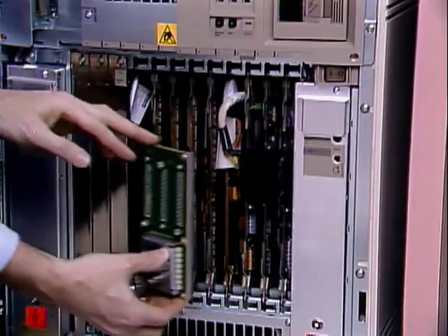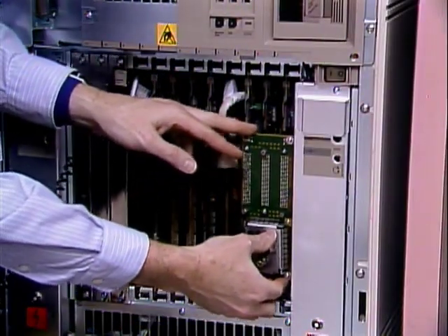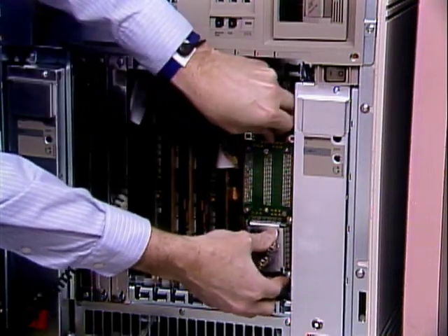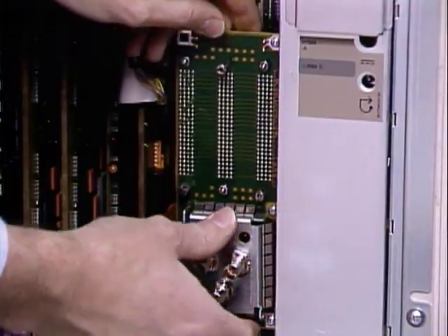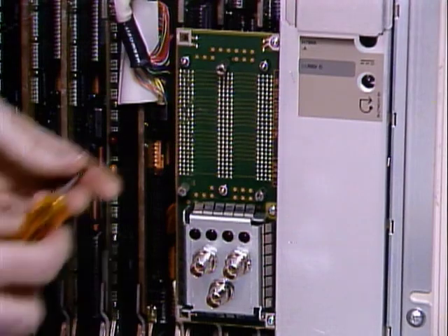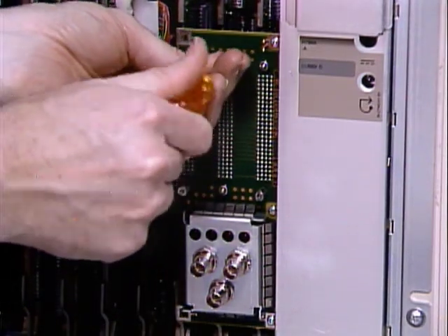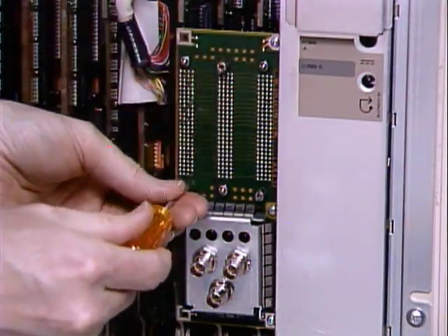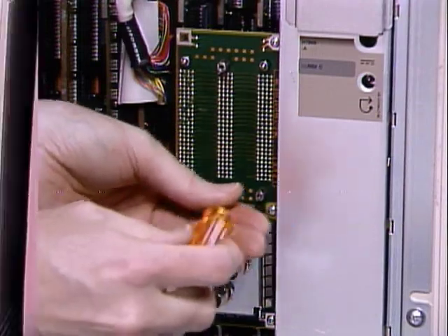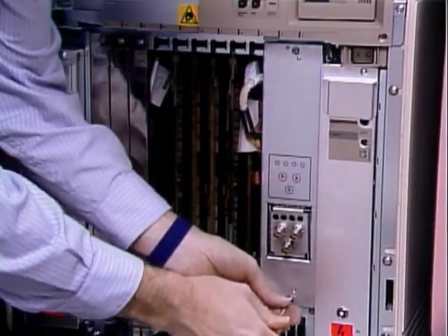After the graphics module has been replaced, replace the HDI front plane. Carefully align the connectors to the modules and apply even pressure to avoid smashing the pins. Tighten the captive screws at an even rate to ensure that the HDI front plane is seated correctly. Finally, attach the cover module and the video cables.